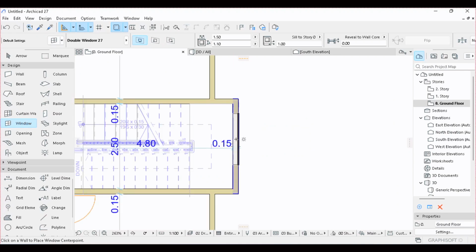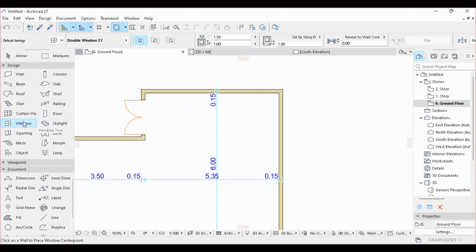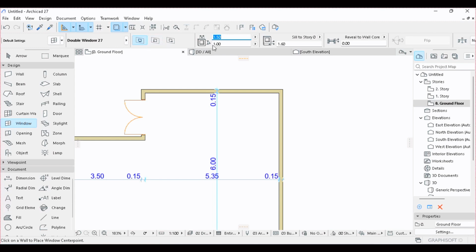For the staircase, I would like the window to be where you come down here from the first story. I want it to be above the landing, so you are going to type in 1.60. And the height of the staircase window, more preferably 1 meter, 1.0, and I put it at the center of the staircase, which is here. For the parlor, I like the parlor window to extend to the next story. So for the parlor window, I want it to start from sill height 0.50. I want the window height to be 5 meters, and the width to be 2.0.